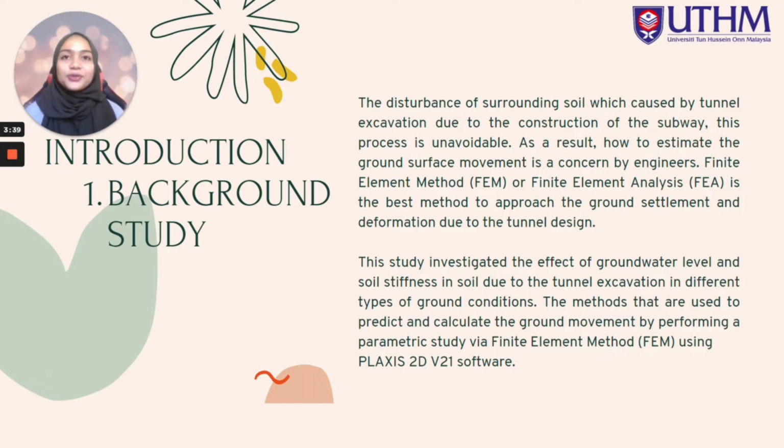Within a mesh, the simulation breaks down the entire model into smaller elements, thus the engineer can test how the different elements of a design interact and perform under simulated stressors. This study investigates the effect of ground movement and the soil stiffness due to the tunnel excavation in different types of ground conditions. The methods used to predict and calculate the ground movement is by performing a parametric study via finite element method using PLAXIS 2D, version 21.